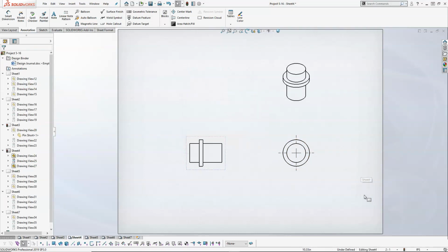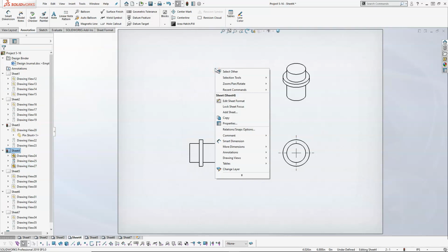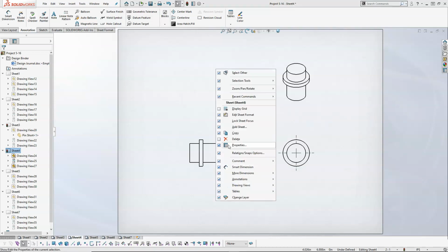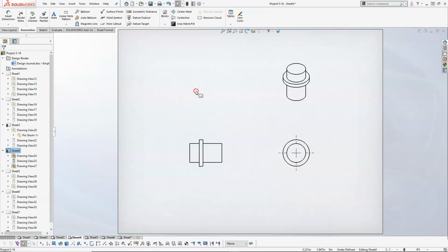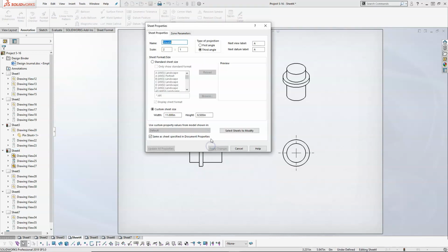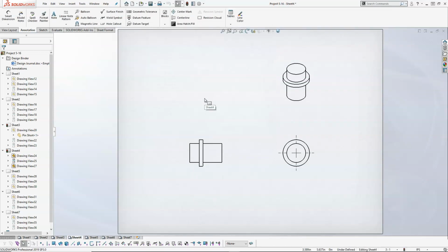And I believe we did a 3-to-1, so again I'm going to go look for the properties. If you don't have the properties shown, I don't know if I've modified this one already, but we expand out the full context menu, come down to customize, and I don't really delete out of this so much as I do the properties, so I would uncheck delete, check properties, and that's going to allow me to pick on the properties, and we'll set a 3-to-1.